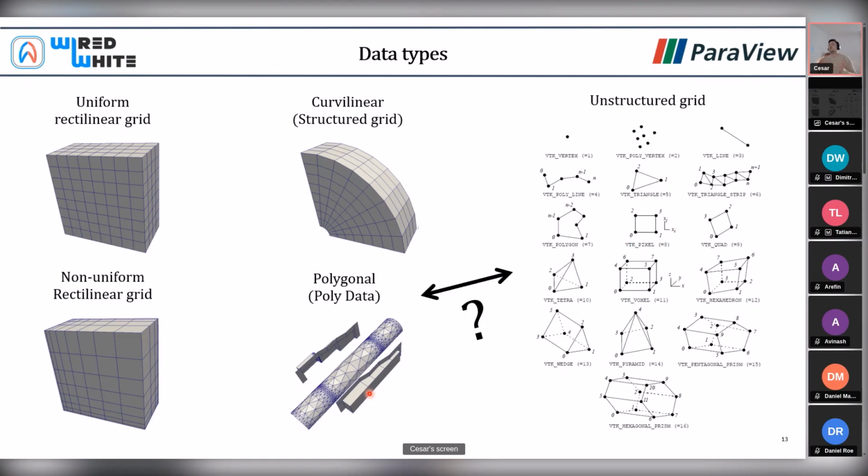Okay, so when you load data into ParaView, you might be loading an unstructured grid, but what is actually going to be rendered and displayed on the computer is a polydata. This process is achieved through the method extract surface, in which the unstructured grid has some faces and edges associated, and therefore you can convert it into polydata.